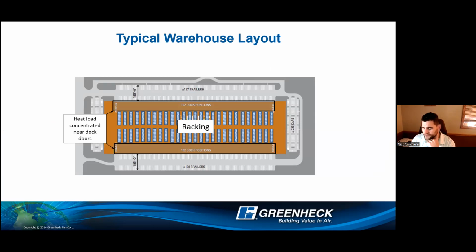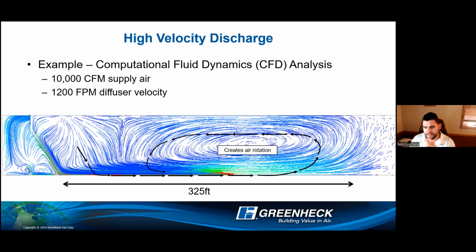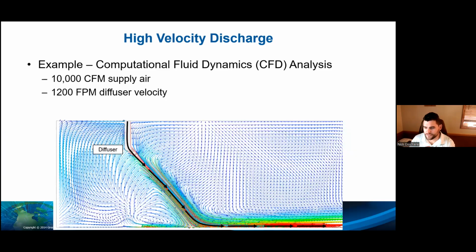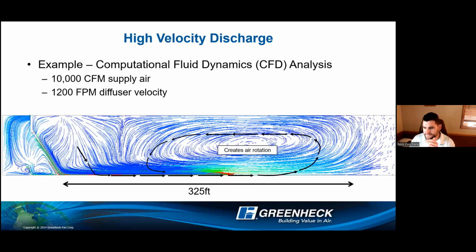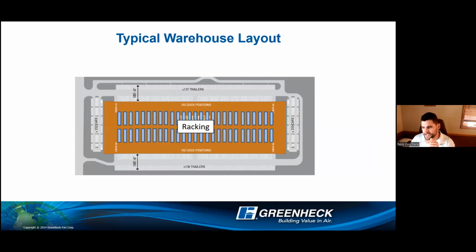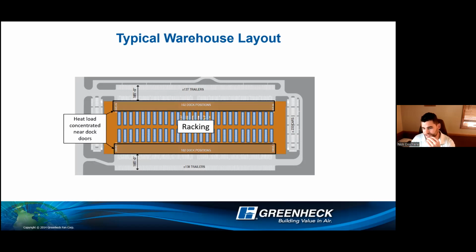That way you have the 45-degree elbows with a three-way diffuser, not blasting straight down and not blasting directly at the doors themselves, but down and away. If you go back here, again, that dock door would be where it says diffuser, and you're blasting at a 45 down and away. So in this scenario, you're pressurizing the center of that space, getting that turnover, and creating that air curtain, that pressurization, to block cold infiltration at all those dock doors, keeping the space comfortable and especially not losing a lot of that heat because you don't have as much loss from cold air infiltration.